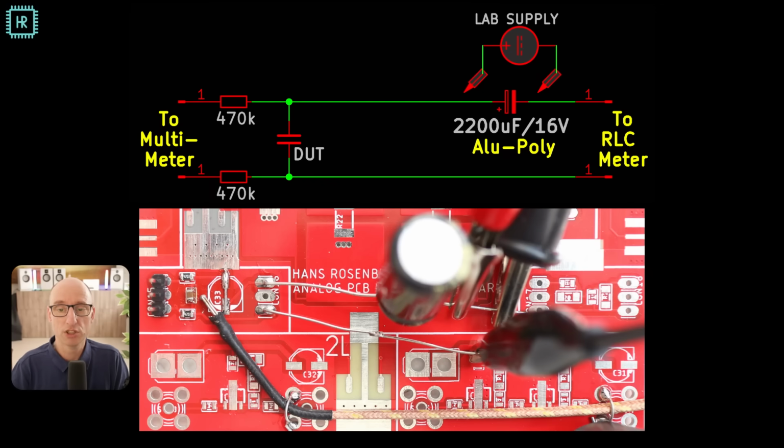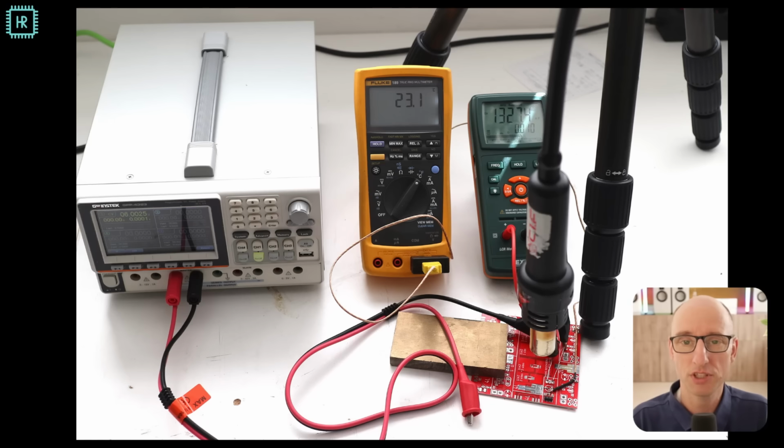In the picture for the actual setup, you also see a thermocouple placed very closely to the DUT in order to measure the temperature. In this picture you can see the total setup. The lab supply to charge the capacitor, a multimeter to read the temperature from the thermocouple, an RLC meter to measure the capacitance, and a tripod to hold a hot air solder gun right above the board to heat the device under test. The rest of the SMD hot air station is not shown in this picture. Setting the temperature is a bit annoying in this setup, as you have to wait quite a long time before the temperature stabilizes. It's primitive, but it works fine.